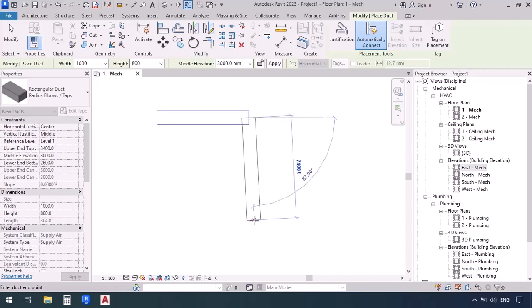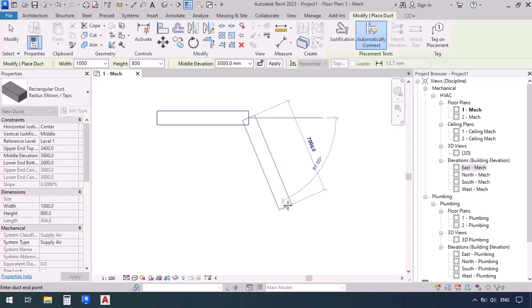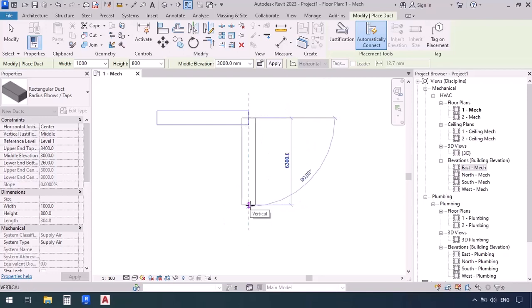For the continuation of the canal, we can determine the facing of the ducts by moving our pointer, as in we can give it an angle, and this angle could be from 0 to 90 degrees. And as for the length, we can either guess it using our eyes, or we could just enter the number that we want from our keyboard.